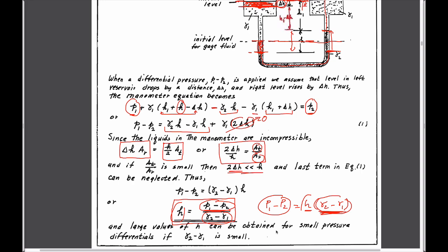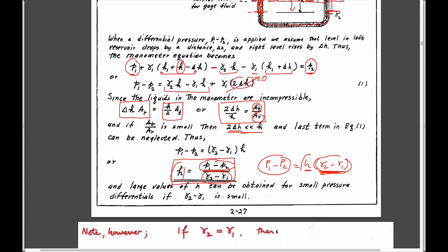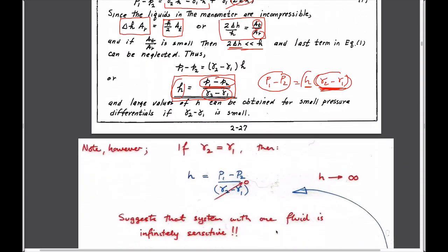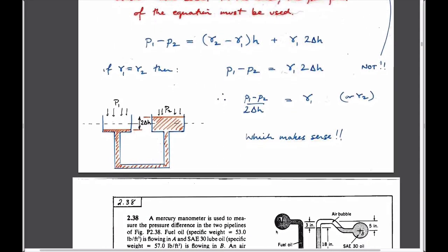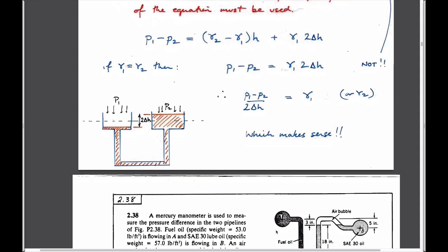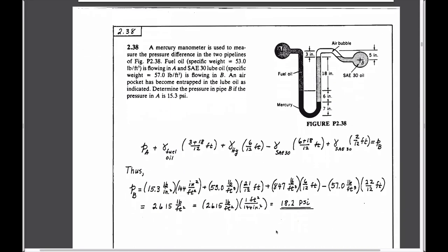Okay. So that's the magnitudes of the use of differential manometer, and some discussion of whether you can use it with the same fluids. You can't use the same analysis if you have the same fluids in the system. But I'll let you go through that in your own time.